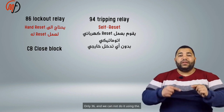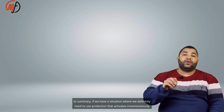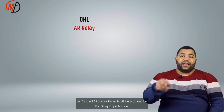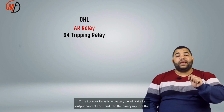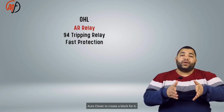In summary, if we have a situation where we definitely need to use protection that activates instantaneously, then we will take a signal from it to perform an action. As for the 86 lockout relay, it will be activated by the delayed protection. If the lockout relay is activated, we will take its output contact and send it to the binary input of the autocloser to create a block for it.